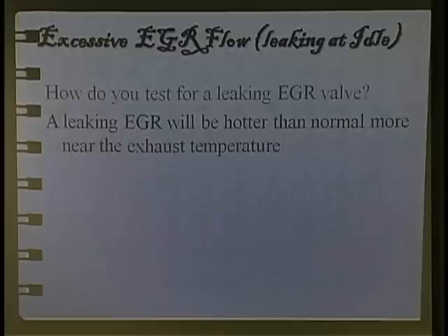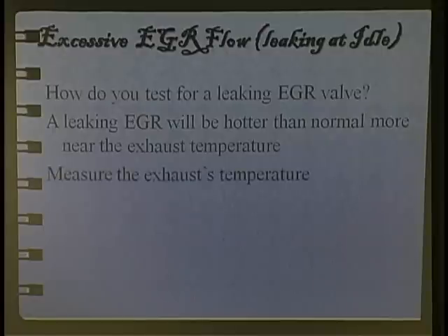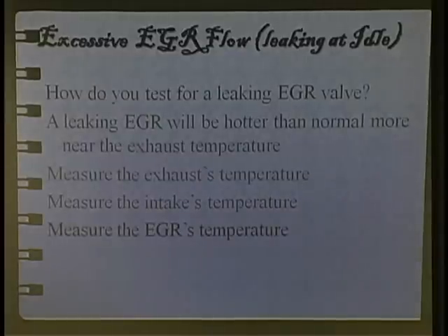Right. So, how do you test for leaking EGRs? A leaking EGR is going to be hotter than normal. Well, what's normal? An EGR that's not leaking is at intake manifold temperature. An EGR that's leaking EGR gases is equal to the exhaust gases. So measure the exhaust gas and measure the intake, and you're using a Raytek gun, not a thermometer.